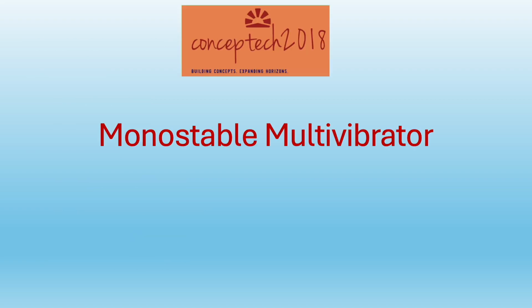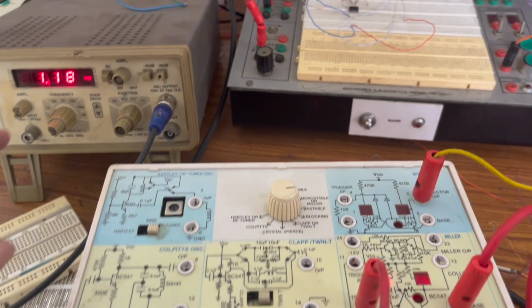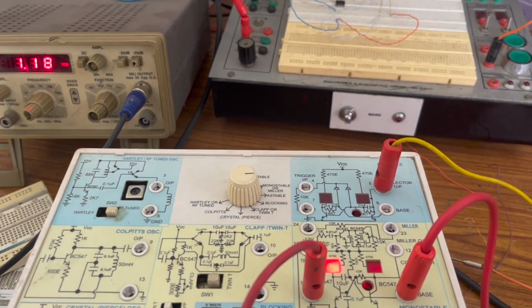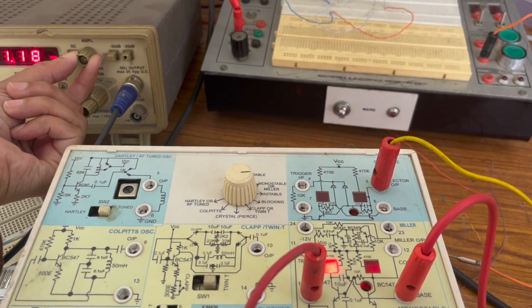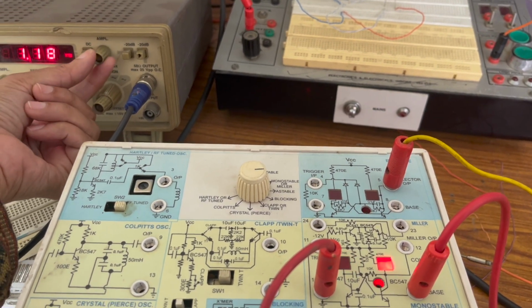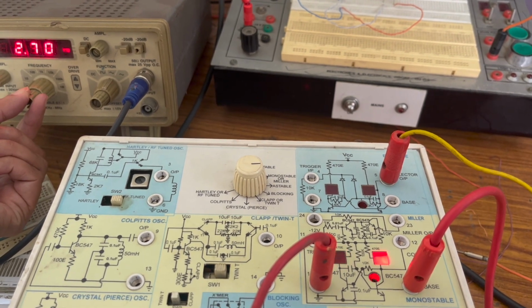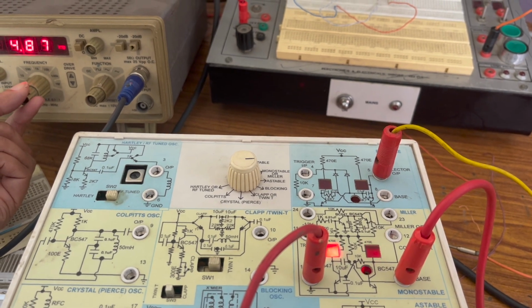The next assignment is monostable multivibrator. Let us see the operation of the circuit in monostable mode. In monostable, a trigger pulse is given for switching to quasi-stable state and it switches back to its stable state. You can observe on the function generator we have given 1 Hertz frequency and we are increasing the frequency of the trigger pulse, thereby the speed of switching is increasing here.